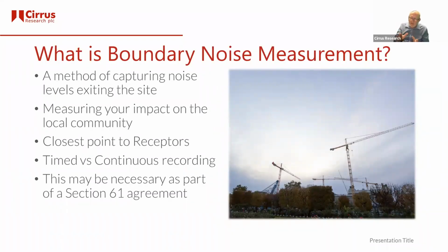We're going to talk now specifically about boundary noise measurement itself. So why boundary noise measurement? Really, we're not interested in how loud the loudest piece of construction equipment is. That digger's really loud, okay, fine. But where are the nearest receptors to that noise?